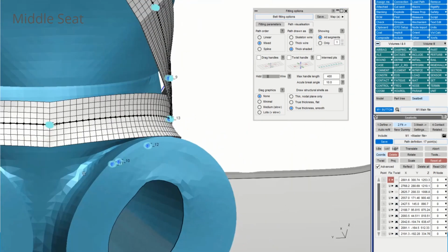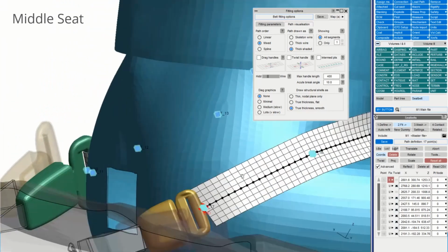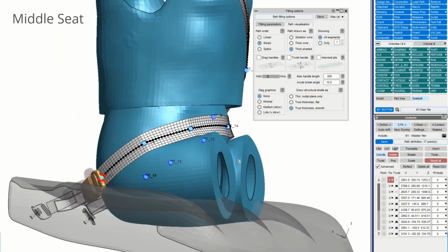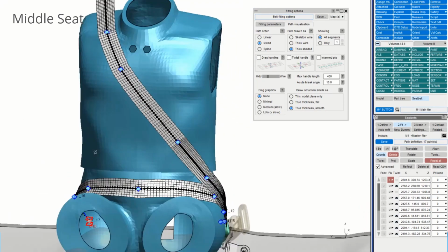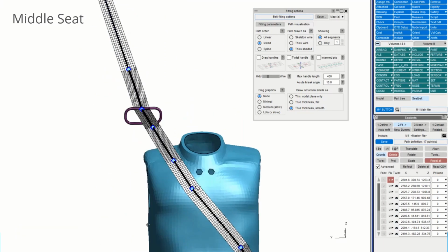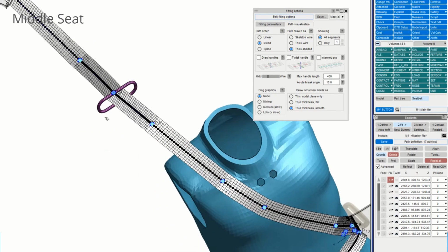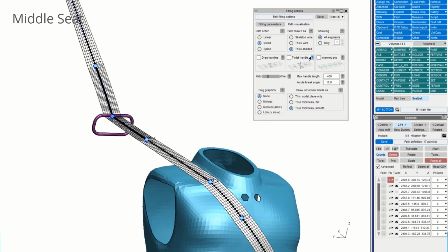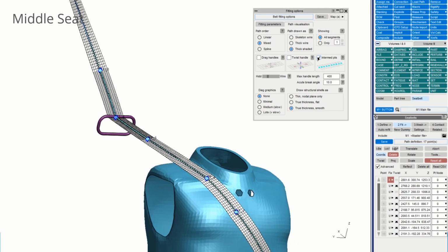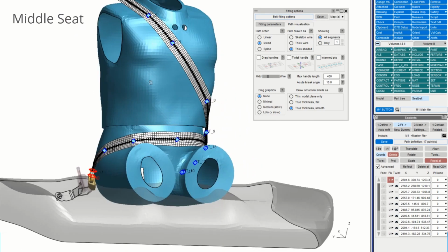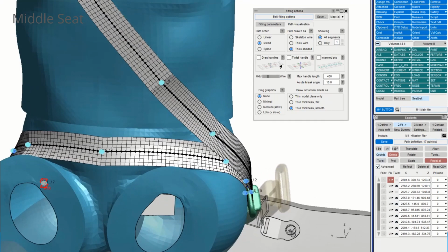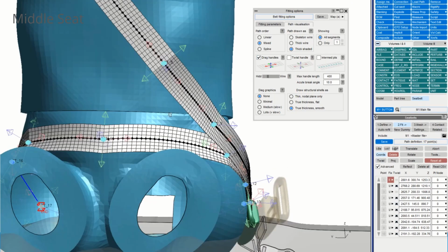To do these rear passengers, we usually use more points on the belt path than for front passengers, and they can be especially helpful when moving the belt apart. In this example up here, I've made a 3mm mesh section, and I did that by making extra path points by clicking intermediate points like this. That lets you set various mesh sizes throughout the length of the belt.